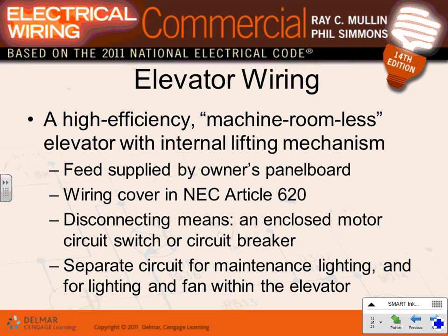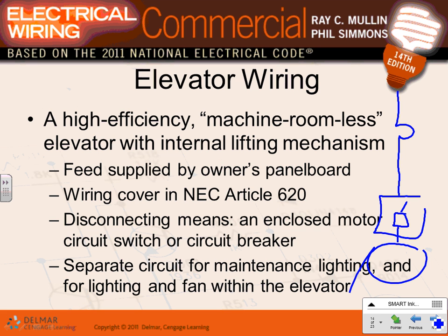The elevator. Okay, for elevators, there's special animals, guys. So you have an overcurrent protection device. Then by code, most codes require you to have a fuse, disconnect, and then the elevator pump itself. Can you write yourself a note here? I can't remember what's the full load current of this elevator. So if you go to this article that talks about elevators, here's what they require you, Jeff. They require a dedicated branch circuit feeding a fuse disconnect that's right next to the pump, the elevator pump.